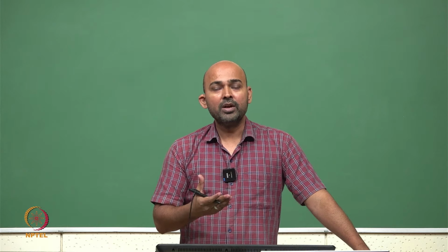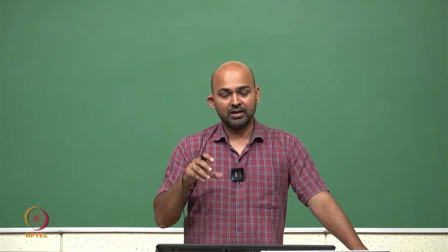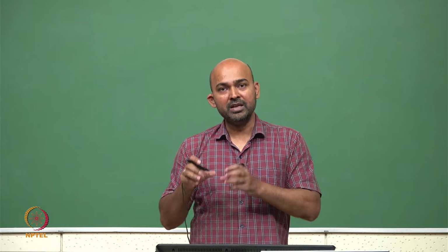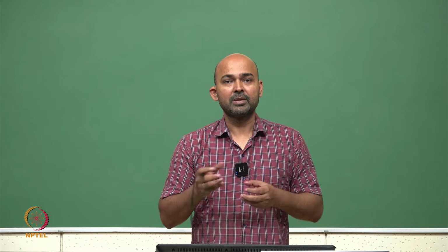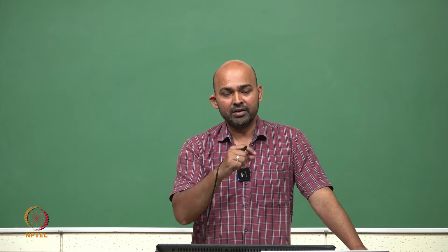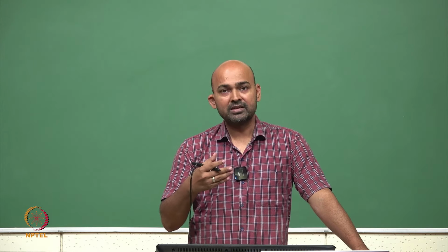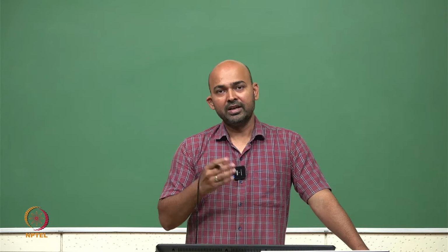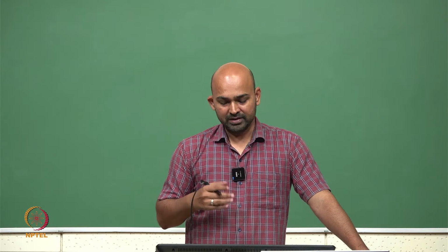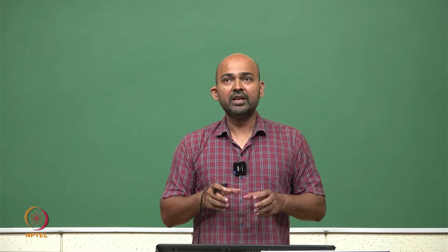Then the components also we need to select very carefully so that the losses occurring due to these components are minimized, and the losses occur generally by the parasitic capacitance, inductance and resistance they have. If we have longer wires coming out somewhere, that is going to create extra resistance and inductance in the path of the signal, and that may degrade the signal. So, these are some of the points we need to check very carefully.